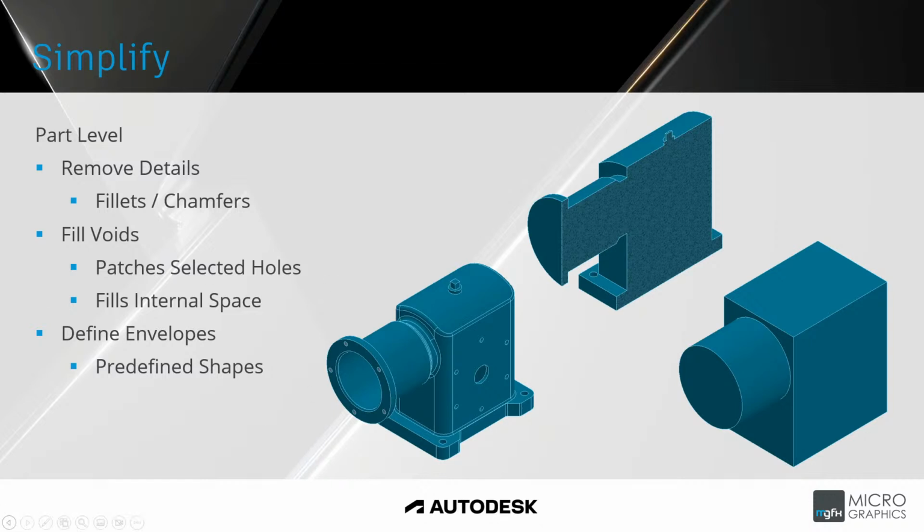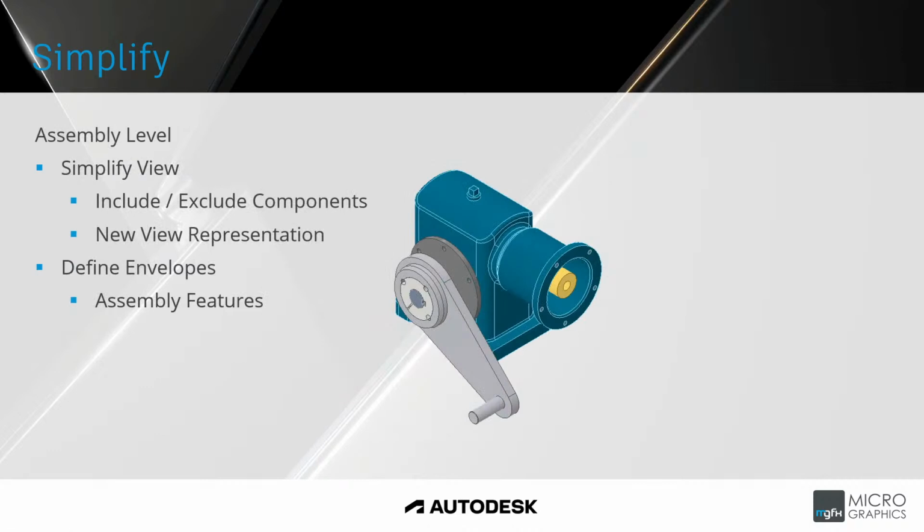I'm going to go ahead here and have a look also at Simplify at assembly level. Slightly different at assembly level. Simplify View allows you to create a view representation where components have been included or excluded from the view. So Simplify View, as I said, creates a new view representation with components that are removed or included. This helps when we move on to the Simplify process that allows us to create substitutes, which we will see a little bit later on.